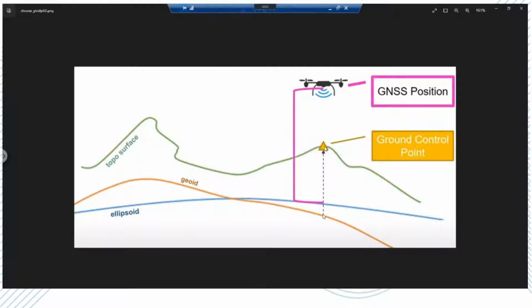Well, we have several tools now online that you can actually do these calculations fairly easily. Actually, we have one really good one in one of our marketing pieces. I believe it's through NGS. Yes. And you might have done that piece, Eric. I think it's one of our RTK workflows. Yes. And of course, we can put the link down for you guys so you can review this. But you would simply take one image, paste the lat and long from that image into the website, and it will calculate that offset. So once we know that offset, let me guide you through Correlator and where you would input this altitude offset to account exactly for this.